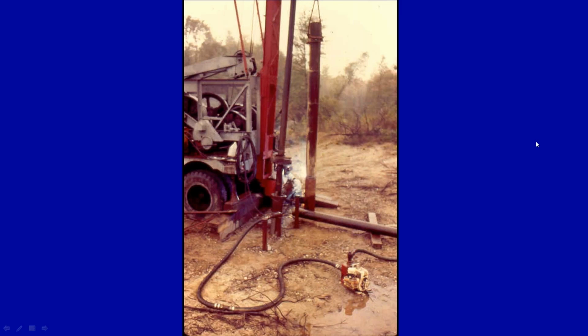However, in Auburn, Massachusetts, we put in the test well. It did 40 gallons per minute. We moved 2 feet away and put in an observation well that only pumped 15 gallons per minute. We moved and put in an observation well 2 feet away on the opposite side that pumped 60 gallons a minute, and then moved and put in the 8-inch well at this location 2 feet from here, and it pumped 200 gallons per minute.